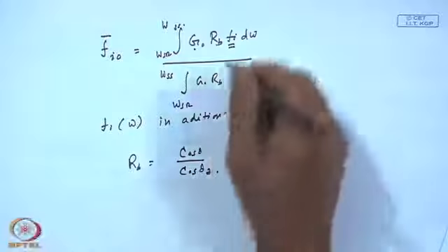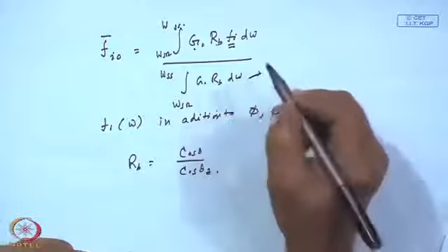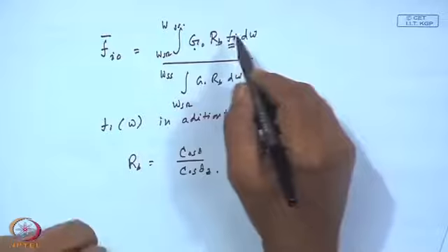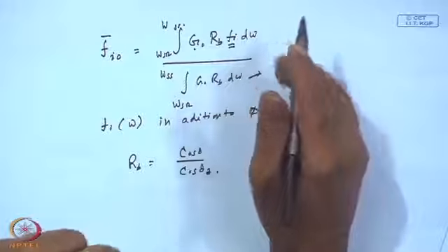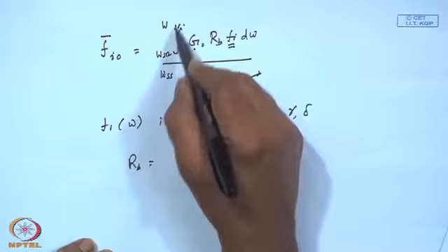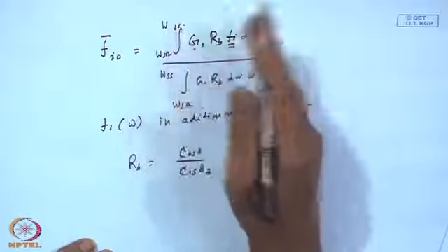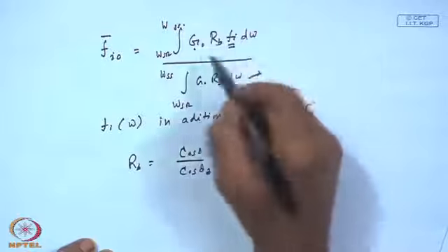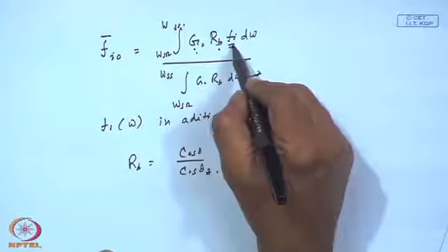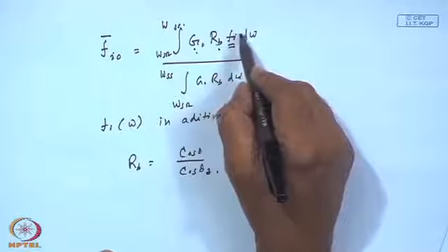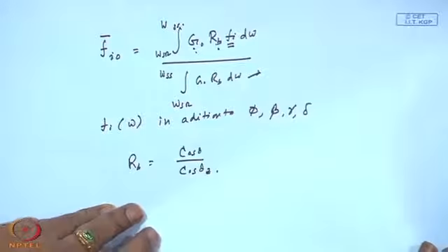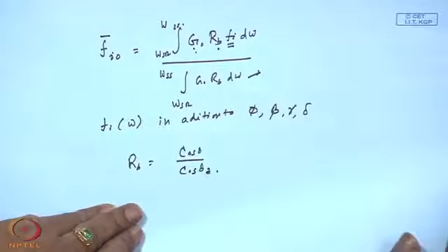We may or may not be able to do an analytical integration for every case, but nevertheless the average value over a time period, a day or the monthly average day or between T1 and T2 during a day, will be G0 and the instantaneous Rb multiplied by the instantaneous Fi, if I have an analytical expression for this, upon the radiation falling had the solar window not been shaded.